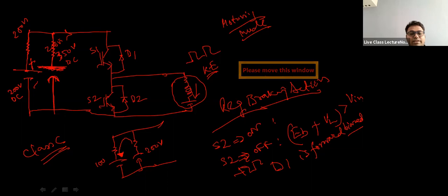So if it is at higher voltage, and if you are keeping the vehicle at rest, it will slowly keep on charging the battery, right? But if in the next moment, say after 2, 3 seconds only, you want to go to motoring mode, what will happen? The voltage of the capacitor will get discharged till it is equal to the voltage of the battery. Is it not so? Yes.